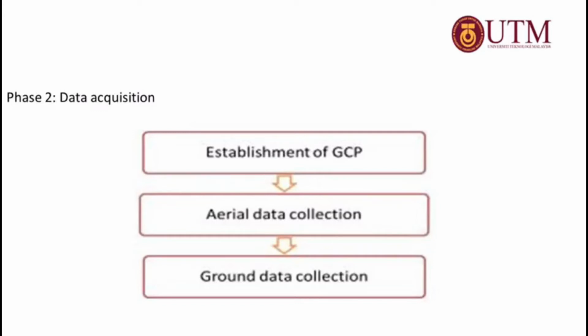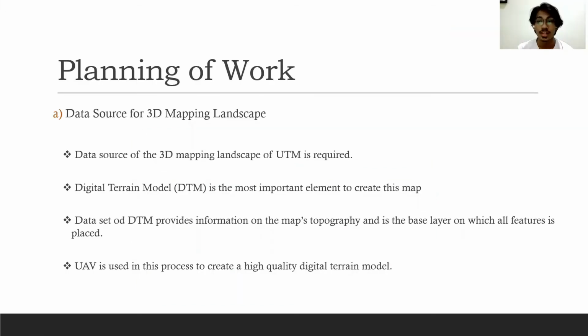Firstly, the laser scanner Topcon GLS 2000 needs to be set up on a tripod, followed by leveling and centering the instrument. This step is important because the instrument must be leveled correctly and plumbed directly on the station point on the ground in order to minimize the error in measurement. After setting up the laser scanner, the bearing of coordinates of the back station were set in order to define the fore station. The line of sight of both back station and fore station will align.